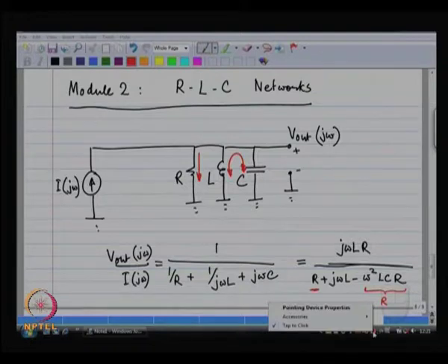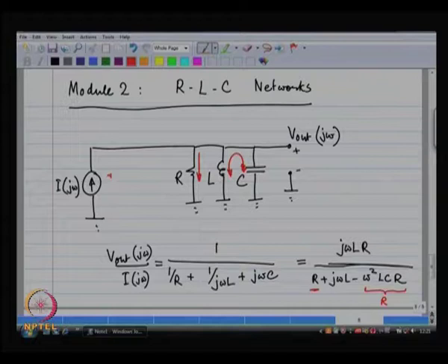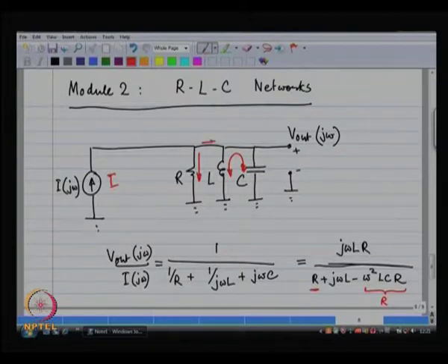So, suppose I apply a current I at the resonant frequency. So, this is I, as I have said. Then presumably at resonance the inductor and the capacitor together, in shunt, look like an impedance which is infinitely large. So, there will be no current going through this section, together they look infinitely large. So, no current goes through to the inductor and capacitor together. So, all of the current I is going to go through the resistor.